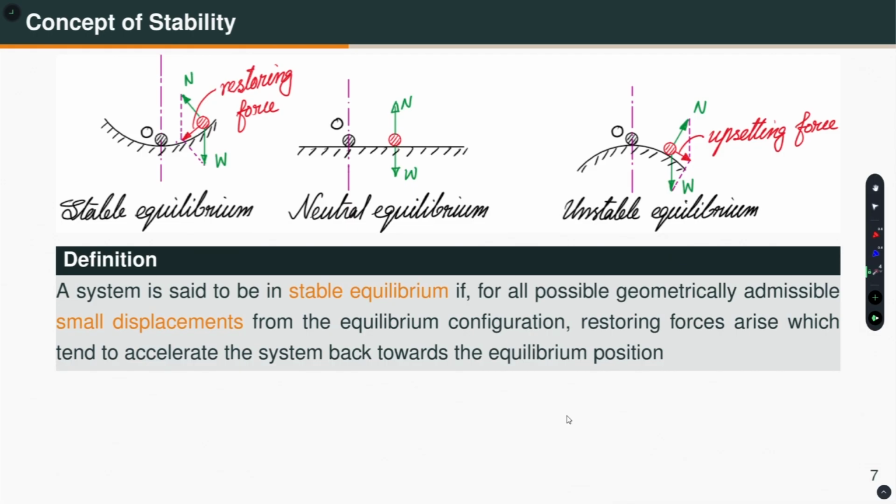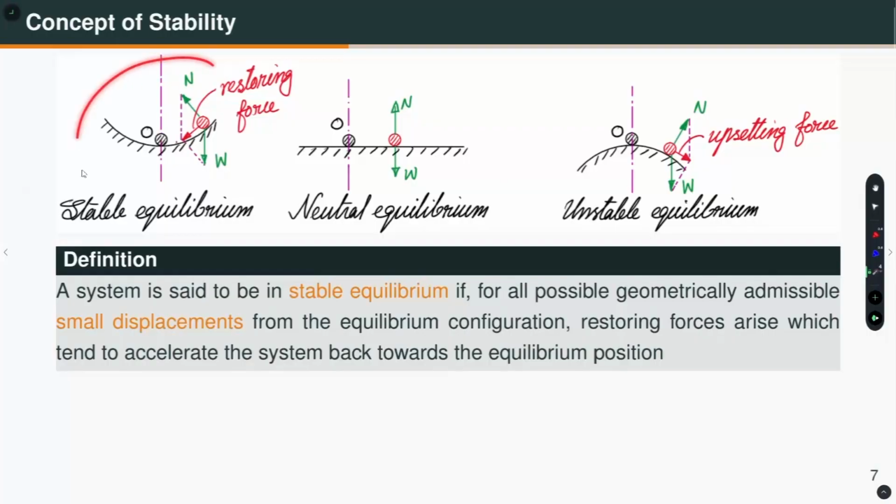Okay. So, let us review a little bit some concepts of stability, which you may have done in your mechanics of solids class. Let us say you take a football and cut it into two and take a small cricket ball and put it inside it. That is what I am trying to show here, right. Now, if you move the cricket ball a little bit, disturb it and release it, what happens? It will oscillate and eventually come back to its original equilibrium position. Why?